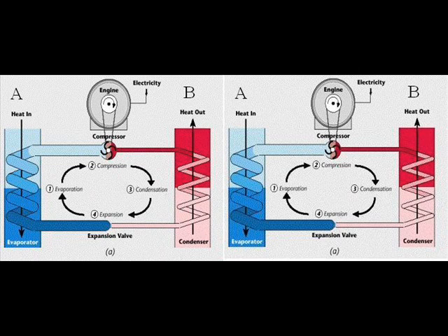By combining the two, it ends up being 11.6 watt-hours of heat energy moved by spending 2 watt-hours of electrical energy input. Since 11.6 over 2 is still the same COP rating of 5.8, which is convenient.